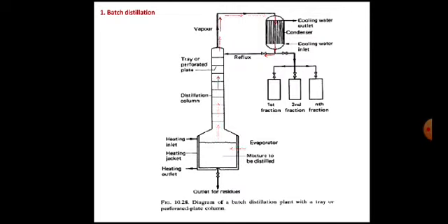It is called reflux. This is done initially so that the temperature of the distillation column can be adjusted. So initially there is a reflux of the liquid that arises from the condenser, called the condensate, back into the distillation column.